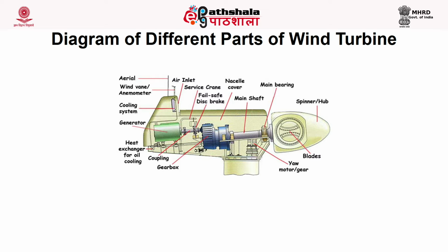Transmission and control. In this part, the rate of rotation of a large wind turbine generator operating at rated capacity or below is controlled by varying the pitch of the rotor blades. The transmission options include mechanical systems involving fixed ratio gears, belts and chains, singly or in combination, or hydraulic systems involving fluid pumps and motors. Fixed ratio gears are recommended for top mounted equipment, and it also consists of the supporting structures. The wind turbine converts the energy in the wind to the rotary